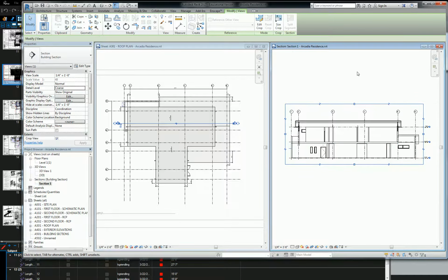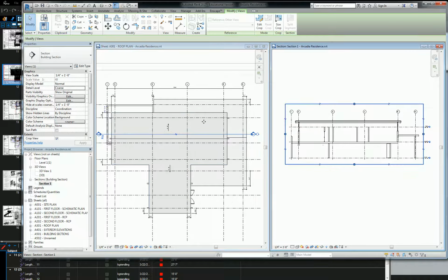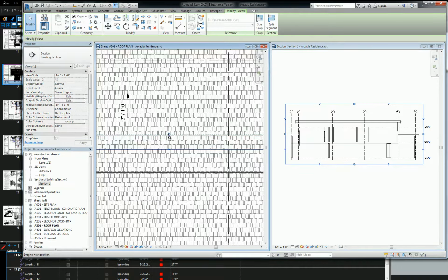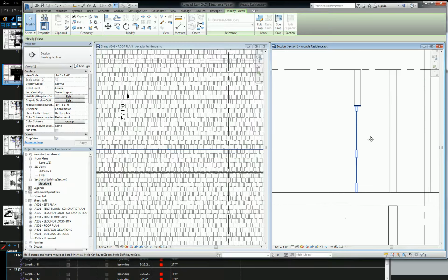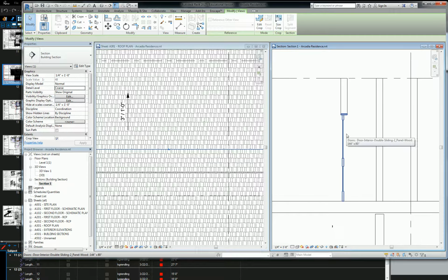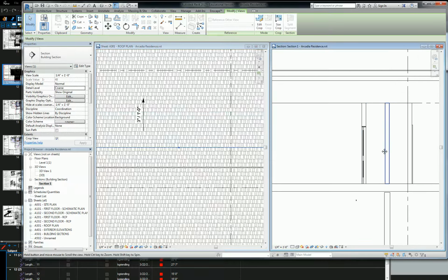Okay, so I'm talking about the anatomy of the building section and the depth to which it's cutting and showing everything behind. So this little thing is something I can pull back if I only want to see a certain depth into the building. So if I only want to see the sliver that I cut, I just pull this back to be really shallow, and it shows me only the elements that I'm actually cutting. That's what you see here. It's so shallow that I don't even see the mullions beyond or the door frames beyond what I'm cutting in that exact plane. But if I pull that back a little further, you'll see that door frame pop up. Does that make sense?